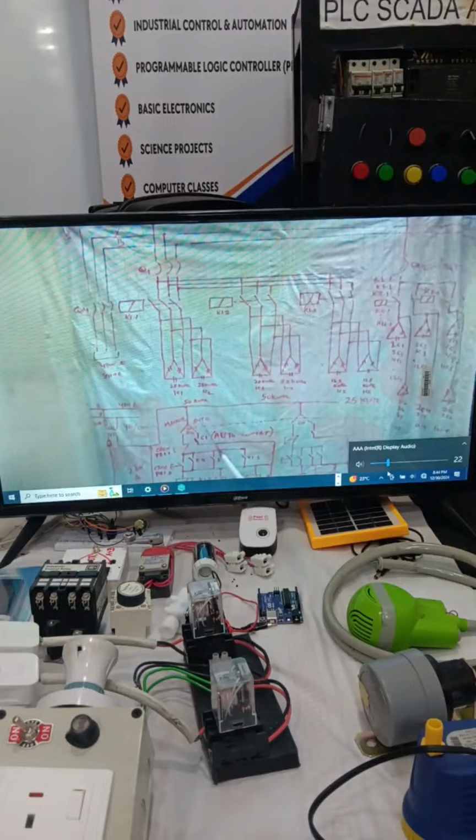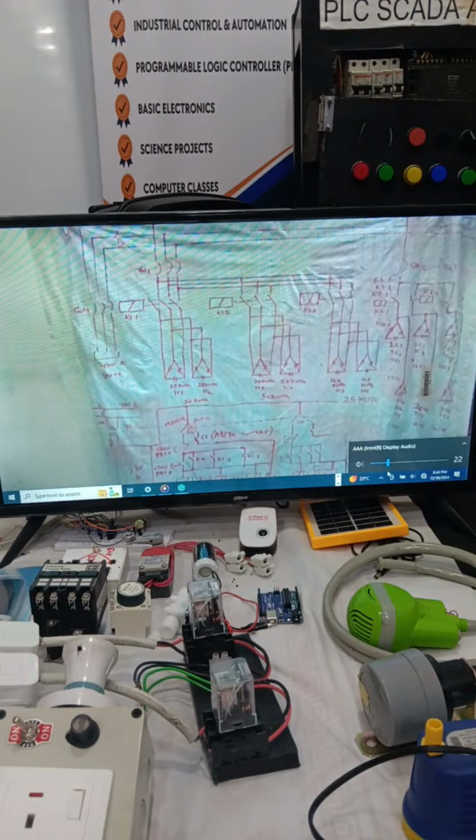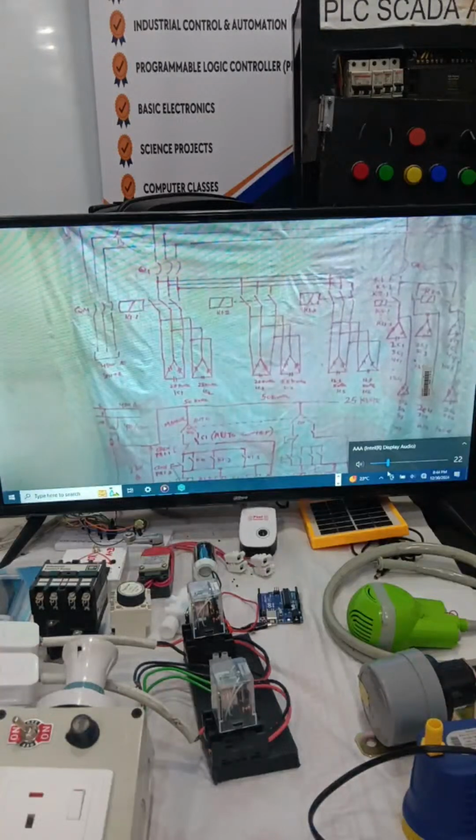In manual mode, when the switch is turned to left, the supply comes here, then it passes through a stop push button, or an open push button. It has a normally closed contact. Normally closed means in normal condition this contact always remains closed. And this is one closing push button. This is a normally open contact. These are all spring operated. So when you press this, the current comes here and the contactor gets supply. But when you release this push button, the contactor goes off.